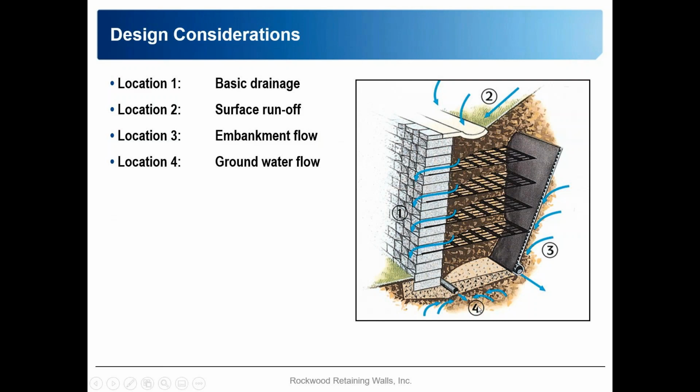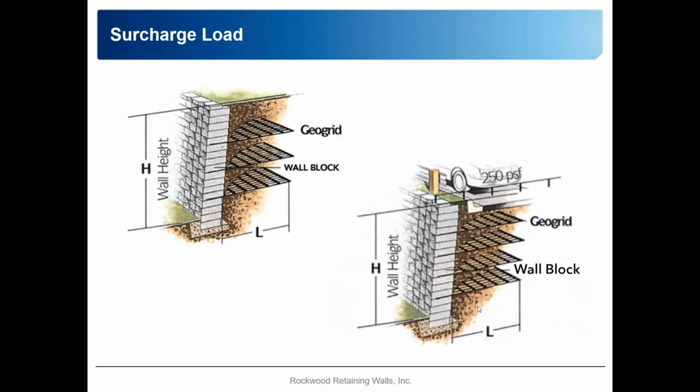And then number four is the drain tile. We talked about that in the cross section of the gravity wall and reinforced wall slide. Again, it's important to have a plan. These drains will catch water, but we have to make sure we get it out from behind the wall, or it will saturate the foundation.